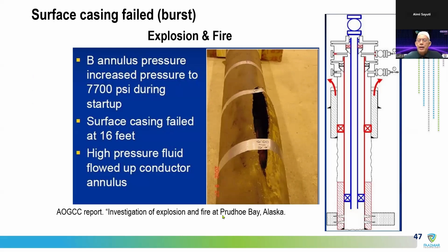Normally, contamination from formation fluid is not much, because when we do the cementing, we are in an overbalance situation, so no fluids are coming in. But some of the fluid, here considered a gaseous fluid, for example some of the gas sands have some CO2, that when we do the cementing job, CO2 starts to come in and try to contaminate our cement.